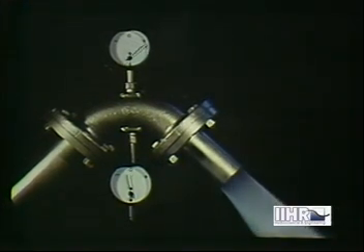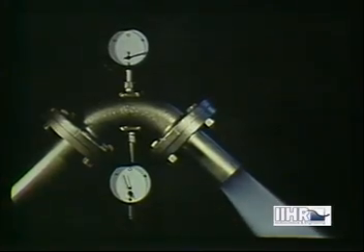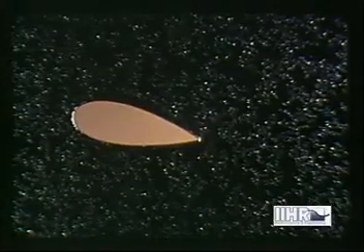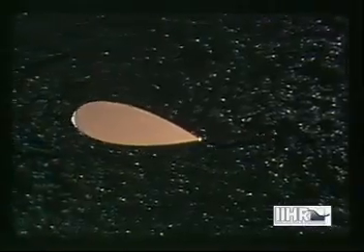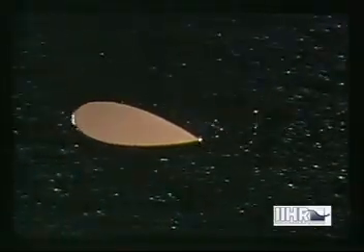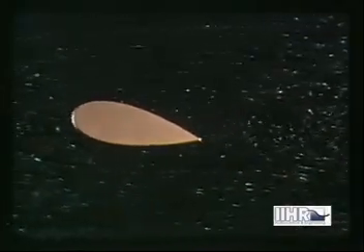Often, of course, as in the case of the elbow, the pressure-velocity relationship is more complex than that for irrotational flow, and the meter must then be calibrated. One reason for the failure of a fluid to move according to the flow net is the phenomenon known as separation, which occurs in boundary regions of too rapid deceleration. As we shall see in a subsequent film, such separation is often the result of appreciable rotationality due to viscous shear along even a smoothly curved boundary.